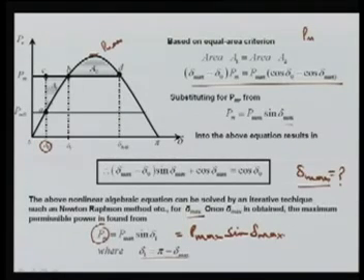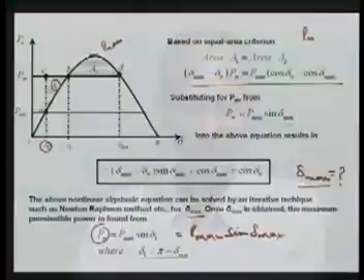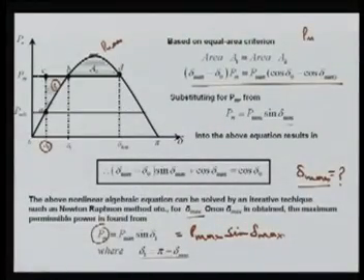But for a sudden increase, the machine will be accelerating and decelerating, because here is the accelerating power, here the machine is decelerating, here it is zero, and here again accelerating, and so on. This area A1 is called accelerating because PM is more than PE, so your machine will accelerate and store kinetic energy.